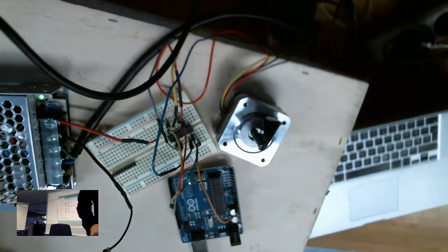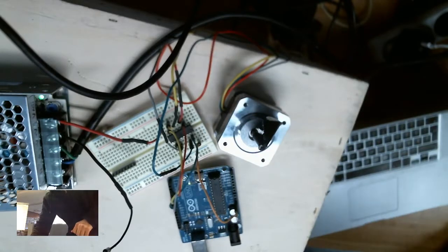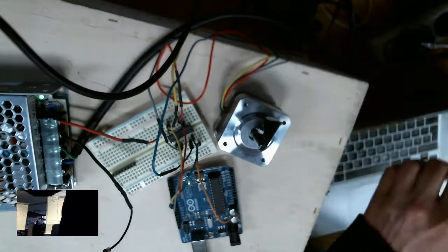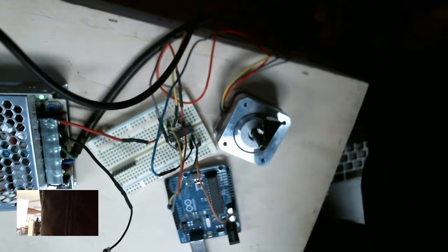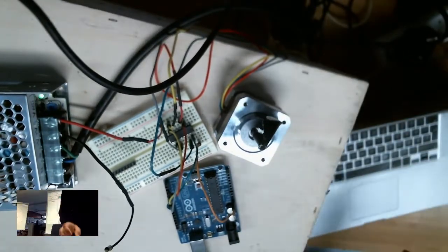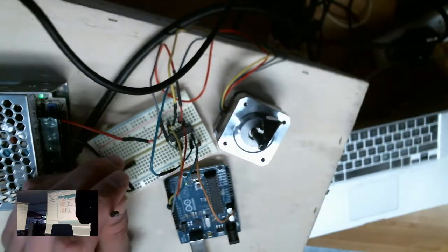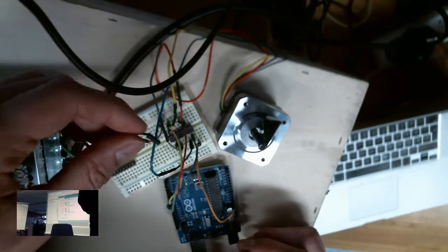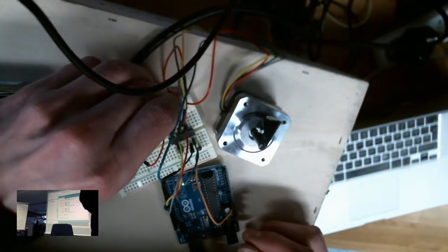And yeah, so there's one last thing missing in our design. That is that we haven't connected the grounds. So I'll disconnect the power supply for one moment once more. So here, as you see, this ground is floating. And in order for it to work, we need to connect it to one of the pins in the center